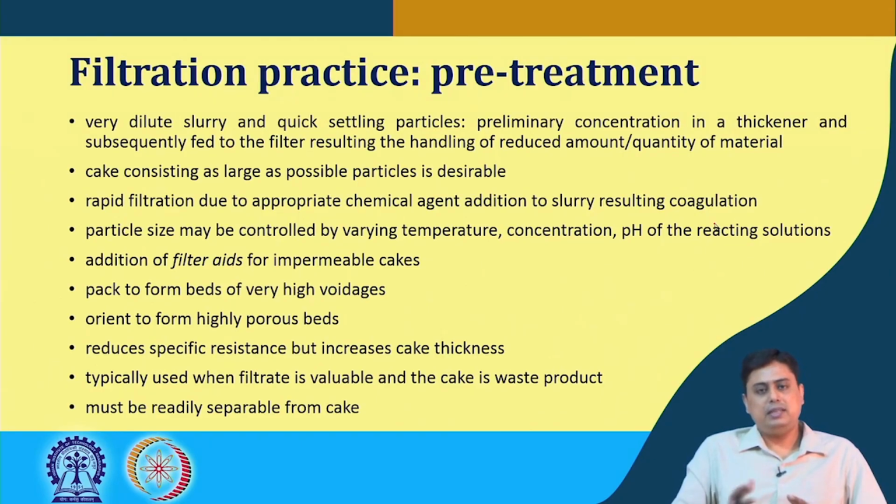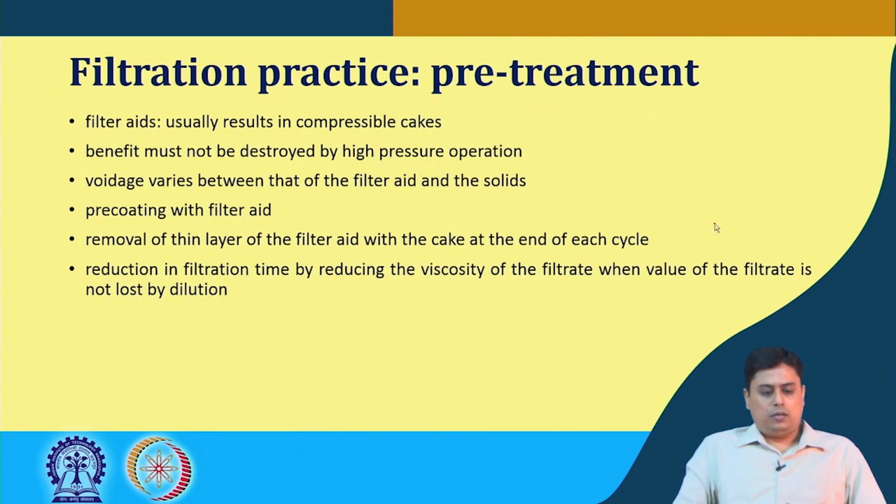So, it has to be easily separable from the cake. This usually results in compressible cake, because as there are high voidages, if you apply high pressure, this voidage changes. So, the benefit of adding filter aids must not be destroyed by high pressure operation.